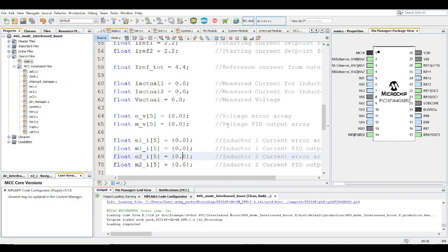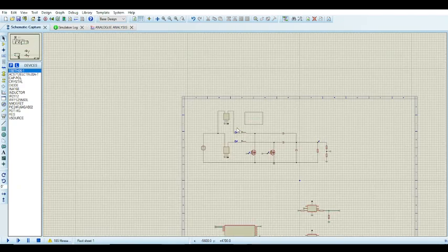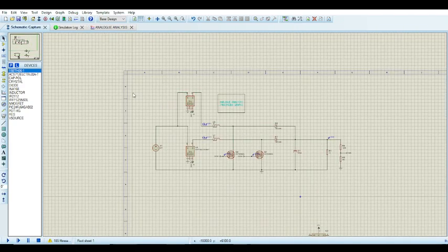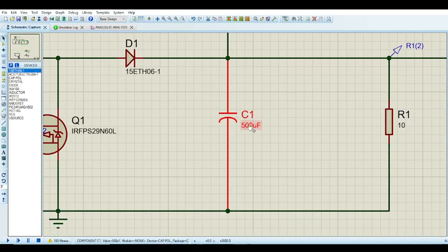And coding it. So this is just how you go about coding it. On any microcontroller for that matter, the coding procedure does not change. As usual, the most important part is the hardware. If the hardware is crap, the code will make it worse. So ensure that the hardware is proper, and of course, first off, the general topology of interleaved has to be proper. Power source, inductors in the proper position, MOSFETs in the proper position, diodes in the proper position, the right diodes, the right resistance.